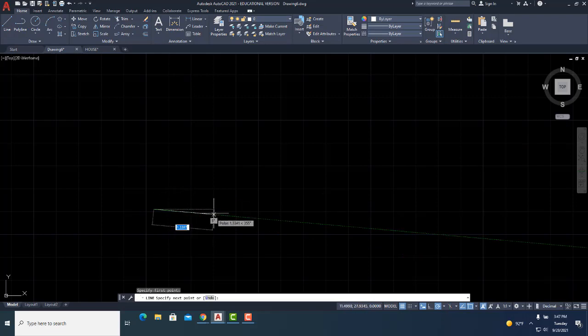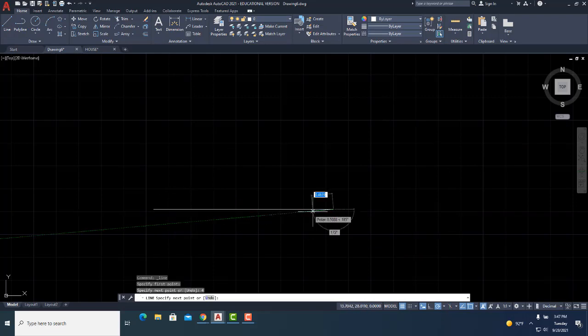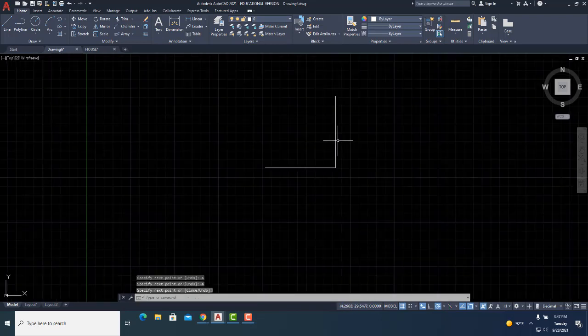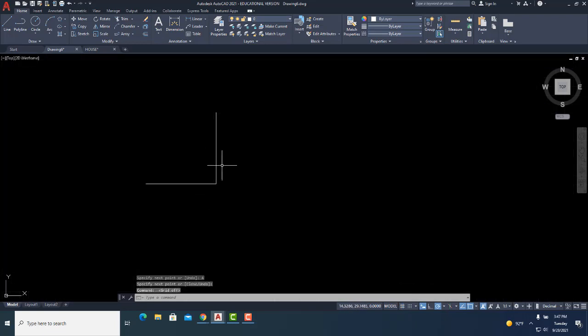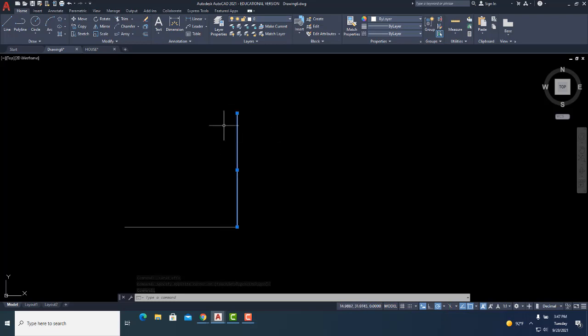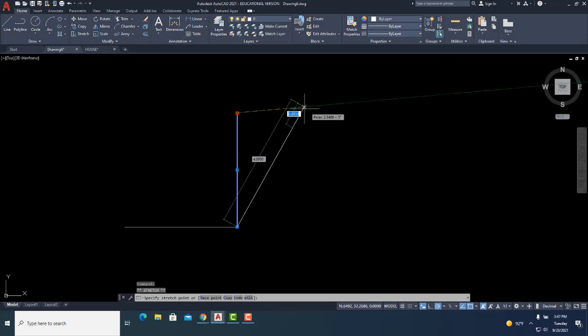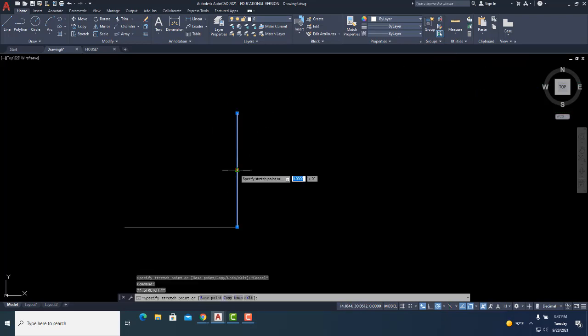So I'm going to draw a line here, and I'm just going to make it 4 by 4. Just make two lines here, 4 by 4. Notice that I'm using line. Now let me turn off the grid. When you have something drawn, you can click on the actual object, in this case the line, and we discussed the grips. This is called the grips. We discussed a couple of weeks ago that you can click on those and modify or make changes.